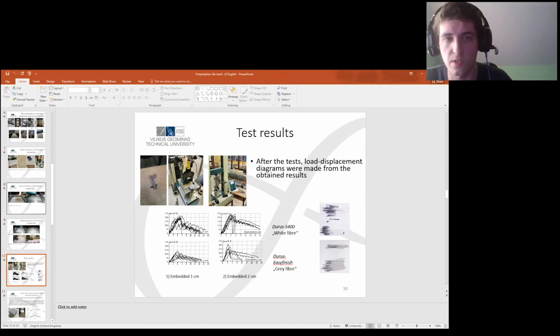Those fibers that were inserted in the top of the specimen, I think they either sank down or were pushed out while the concrete was hardening. A hole would form around the fiber itself, and that changes the embedment length. So a lot of them you could just pull out. The bond strength wasn't as good as the fibers on the lateral plates.